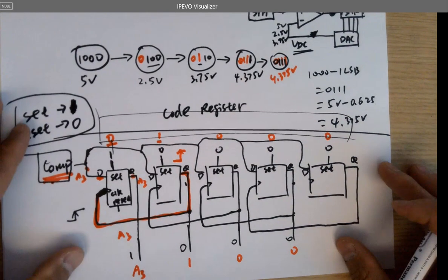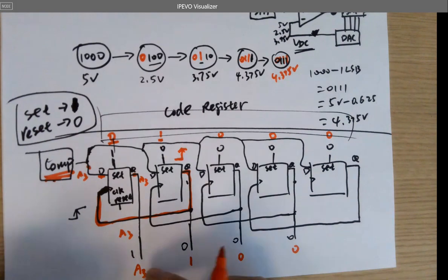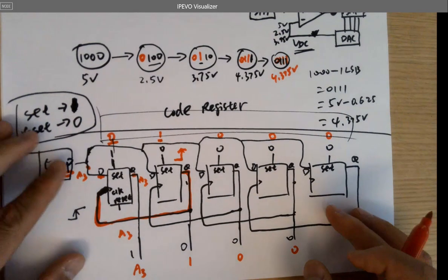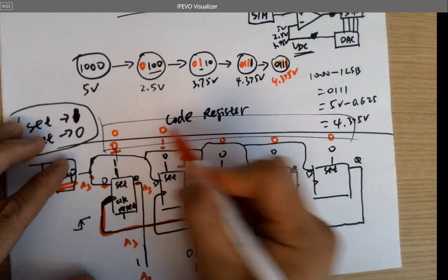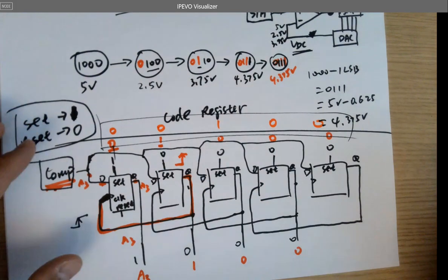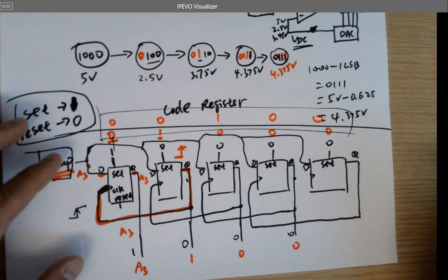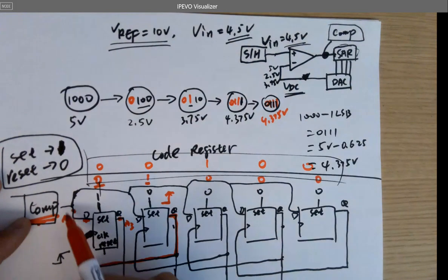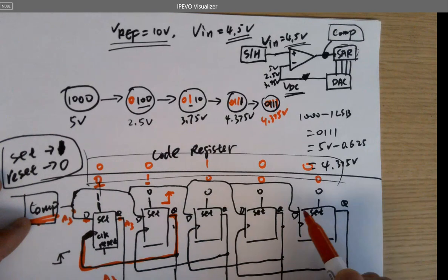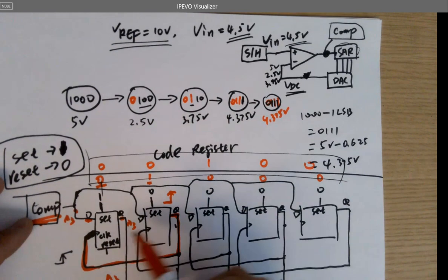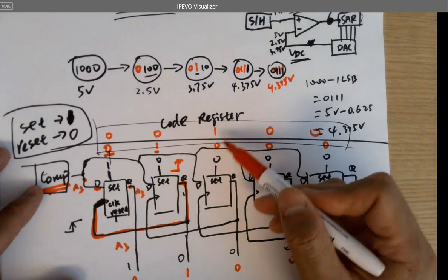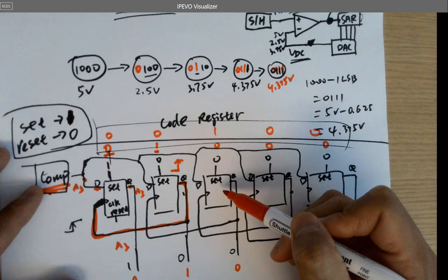The next one. We want to make sure A3 will be kept there, right? It's not being stored, shifted, or changed. So what's the next cycle? You are getting 0, 0, 1, 0, 0, right? The comparator's output from here is still being shorted to all the D's. It's not being changed. It's feeding the data to all the D's, but only one is going to work because you got a 1 for the third D flip-flop.